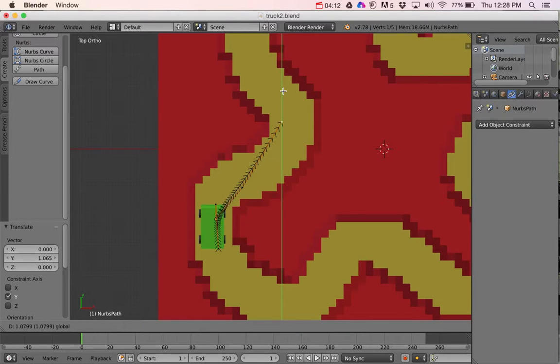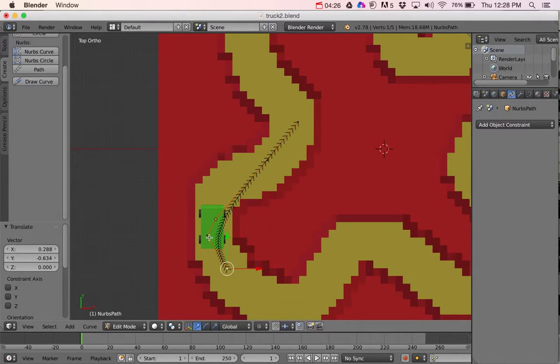The closer together these things are, the slower it should go. You can also press G to grab, and that can also pull these around. Oh, I've got kind of a weird thing happening there. So let me pull that. G to grab, got a point in there. Okay, so once you have started playing with these, and once again I'm just pressing G to grab.